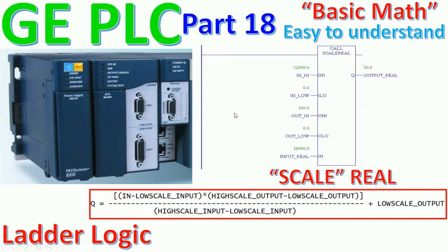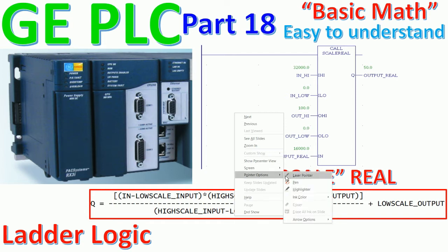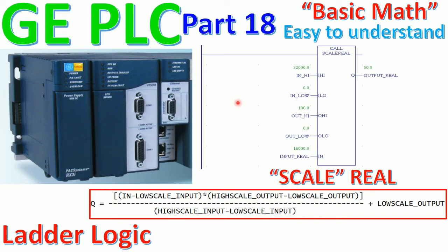Today we will continue our lesson about basic PLC GE, and I will show and share how to create the scale real data type. It means that we scale the analog, for example, but the output is the real value, okay. And here is the formula.